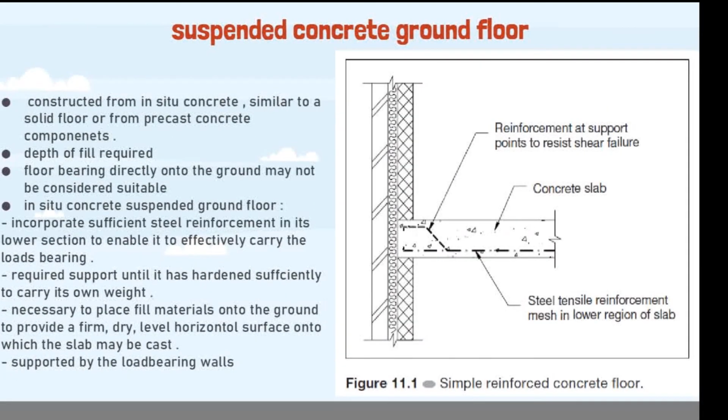And there is the suspended concrete ground floor. Concrete ground floor constructed from in situ concrete, similar to a solid floor, or from precast concrete components, and the depth of fill required. A floor bearing directly onto the ground may not be considered suitable.